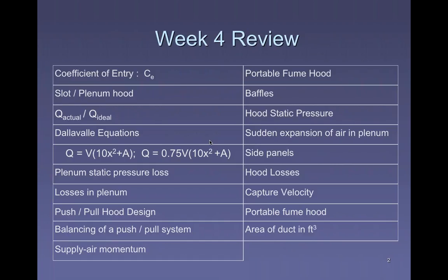The idea that there's certain system effects, like when you suck air in, where you get this area of very high turbulence, where the air is kind of compressed and then expands suddenly. We've got to stay away from areas where there are these kinds of system effects, because we need to be far enough away from those to get accurate measurements of the duct velocity pressure and static pressure. In general, depending on what you're connecting to, that's usually 2 to 6 diameters away from the device, the fan or the hood or whatever. That's duct diameter. In other words, for a 12-inch duct, that would be 2 to 6 feet downstream.